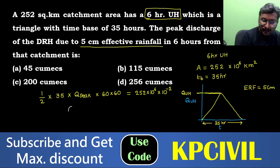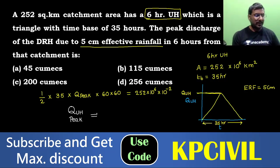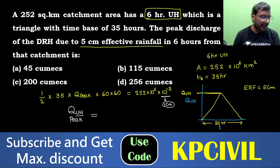Solving this, you will get the unit hydrograph peak discharge. Clear? Half into 35 into peak discharge into 60 into 60 is equal to 252 into 10 power 6 area into 10 power minus 2. 10 power minus 2 is 1 centimeter effective rainfall, which is for the unit hydrograph.